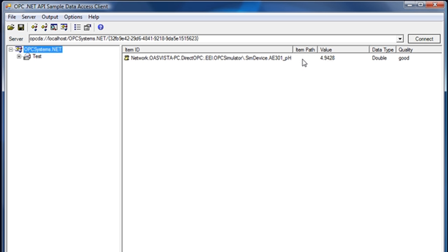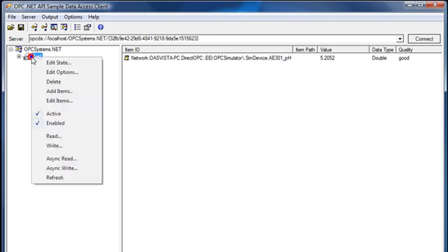And now we see that when the value changes, we are subscribed to that remote OPC server from that remote network node, still using a TCP connection without using DCOM to do the networking. Let me also add another tag to an OPC Systems.net tag.